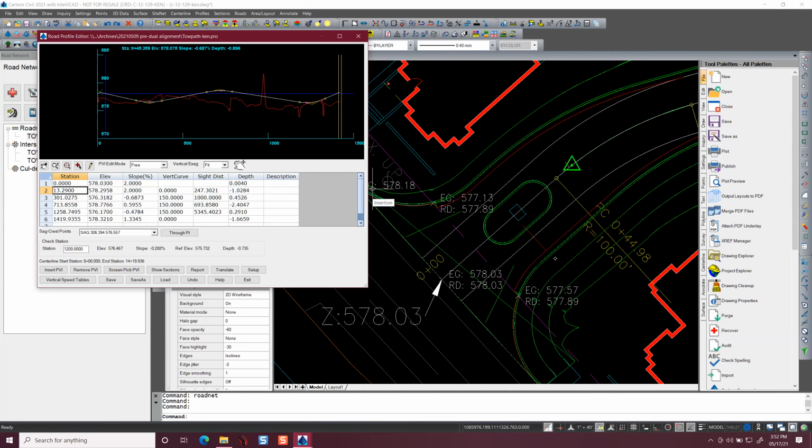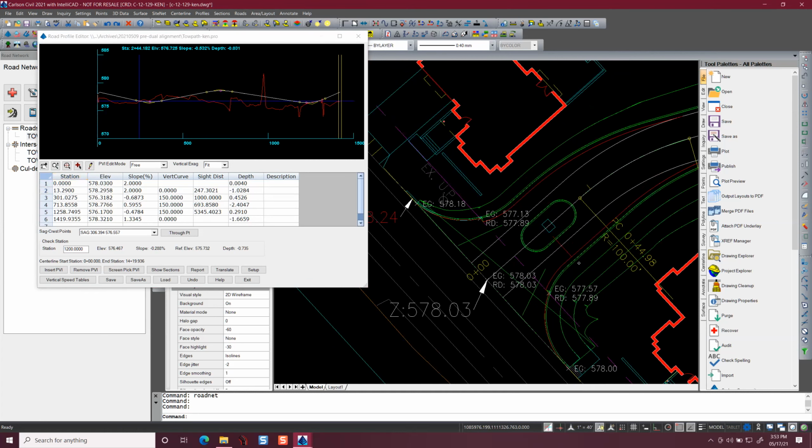So what do you do with the water then? Obviously you're going to catch it here. There's going to be a catch basin right where the property line is, and the pipes will go back toward the pond. But now what do we do with this water that comes down to the edge of pavement? It's not much, and it's not really flat across there, is it? There's very little relief, but I have no choice but to have it flow. I can't put any catch basins in there, so it's going to flow down that crease.